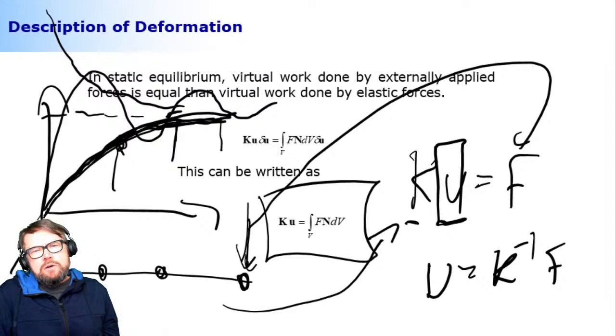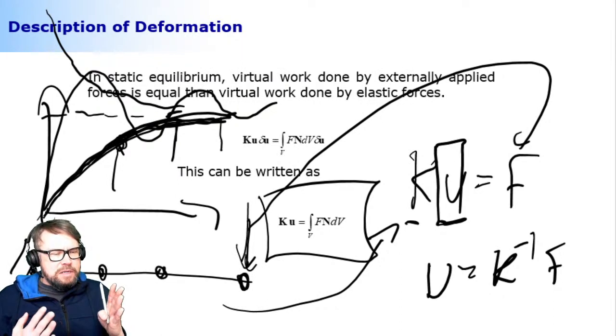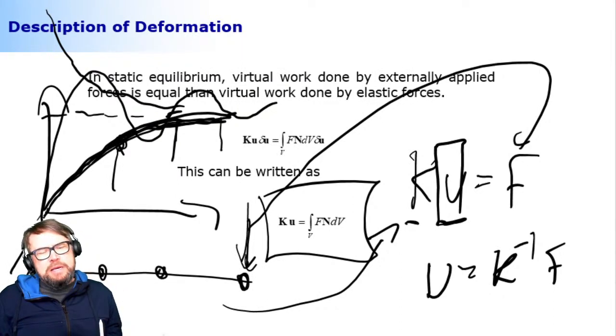Yeah, we never know the right solution. So we never know the right solution. That is a problem in the finite element method because you're using it for problems that you cannot solve by using pre-calculated tables or some simple other methods. So basically, the only way to know if your solution is acceptable is to make your mesh more fine, and then see if the solutions are affected.